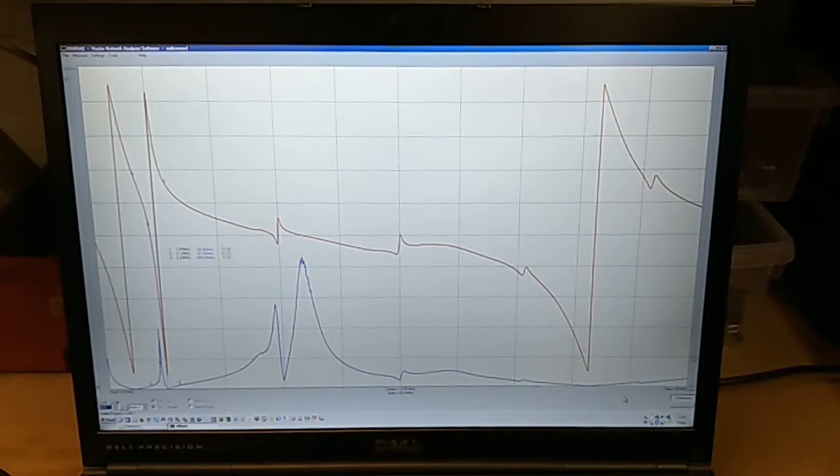But now we are looking at a third resonant circuit as well. So in other words, we have the series tank capacitors, the 4.7 nanofarad tank capacitors, either side in series with the primary, and it's in series with that primary resonant circuit.